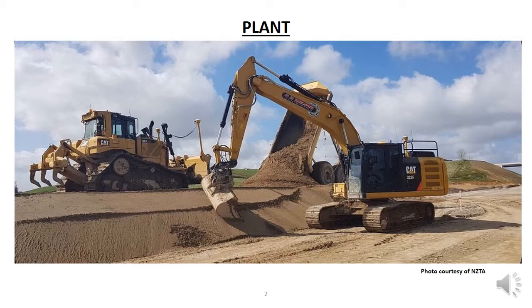We also have water carts to wet the soil, to adjust the water content, or reduce dust nuisance. These water carts are trucks with a water tank and a spray system fitted to them. When we need to dry the soil, we use tractors with discs, which are used to turn the surface soil to allow it to dry better.